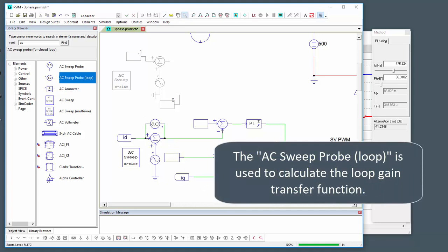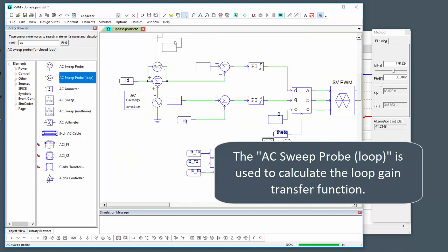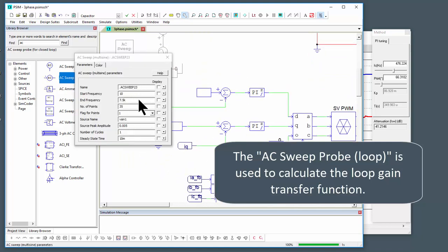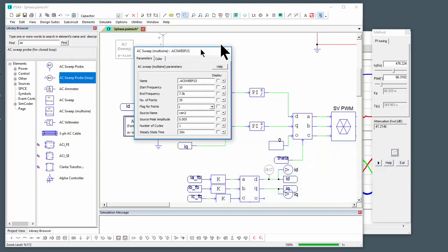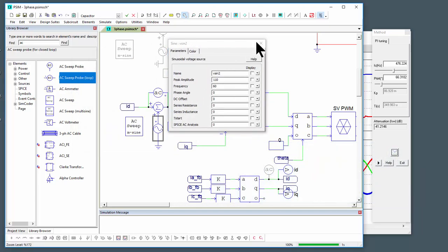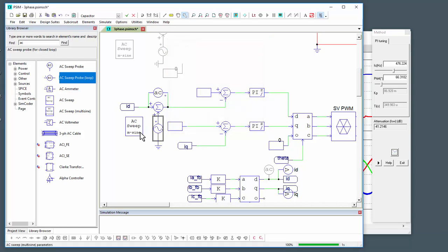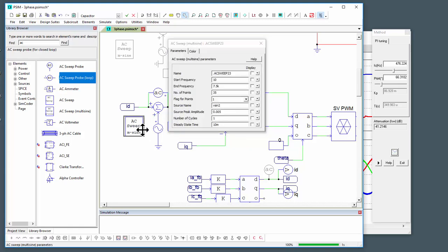So this is different from that other sweep that we were using, which is this one down here. We're going to be doing this one, V sine 2, and we'll change this, V sine 2, that works. Again, these numbers here don't mean anything when we do the sweep. They will mean something in a time domain simulation, but they don't mean anything in a sweep. And we can keep these numbers, V sine 2.